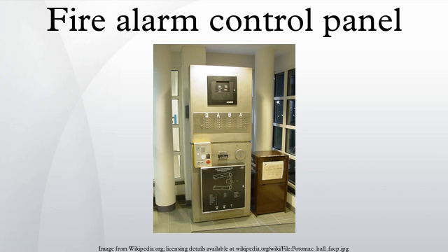The alarm panel can be reset once the device which initiated the alarm is reset, such as returning the handle of a manual pull station to its normal position. Audible silence. The audible silence indicator is used in conjunction with the alarm indicator. It indicates that the fire alarm panel is still in an alarm condition, but that notification appliances have been silenced. While the alarm is silenced, other functions in an alarm condition continue to operate, such as emergency service for elevators, stairway pressurization, and ventilation functions.